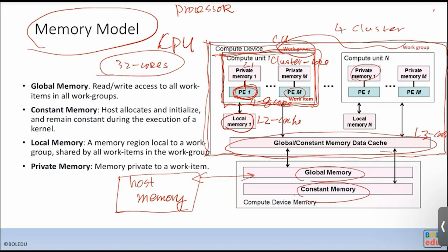So inside the CPU, it has a very sophisticated cache snooping design. For the FPGA, that would take up too many gates. Actually, in a CPU, the cache coherence and the tag memory take up a lot of die size. But the FPGA doesn't do any of that memory snooping.